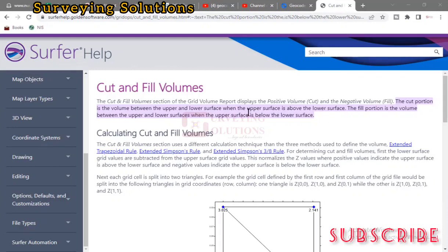We are going to show you that. One surface most times is the base surface, then the other surface is the top surface. When we say base surface, for this particular cut and fill, it might be the level, or the grid, or the elevation you want to get to. That can be your base surface. Then the top surface would be the complete topography of that area.